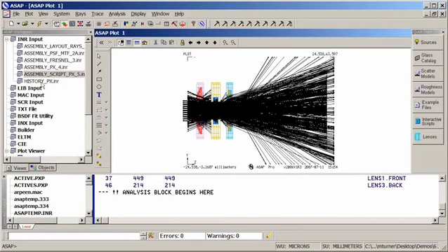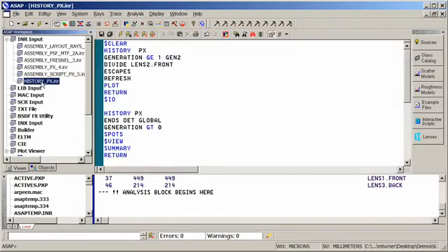So what I might want to do again is to use my Path Explorer, but in this case, let's take a look at how we do it in terms of the scripting environment. In this particular case, what I want to do is look at all of the rays that make it to the detector, and also get an idea of where all of the rays that didn't make it to the detector, at what surface within my design they exited out of the system. This is an example of Path Explorer commands within ASAP.